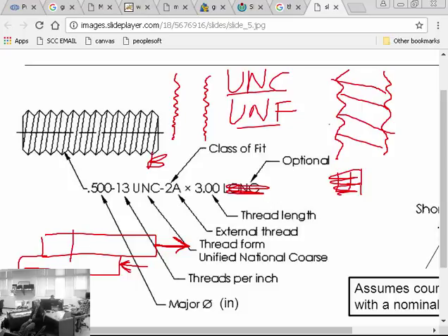Now, back in the day, starting off when we had rivets and stuff like that, we just used the rivet to actually stop this motion by its raw strength in size. Nowadays, we actually use the threads and the connectors to not only help resist the motion, but also to bite down here and here with that torquing ability. We tighten, we tighten, we tighten, because we want these two plates as tight together as we can possibly get them within standards.